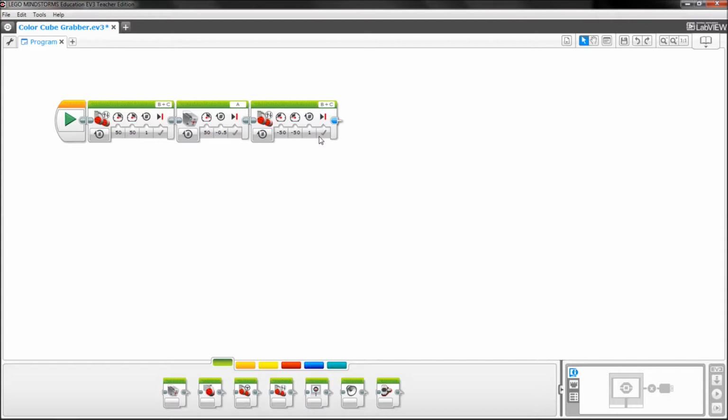We're going to keep the one rotation, we're going to keep the brake. Make sure it's on rotations. We do not want to change that. Now let's reset everything. Make sure your arm is touching the robot controller. Make sure you have the brake a good distance away from the robot. Go back to your robot controller, go back to your program, and run your program again. Let's see what happens. This time it should drive forward, grab the cube, then drive backwards.